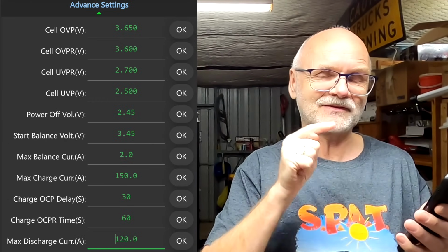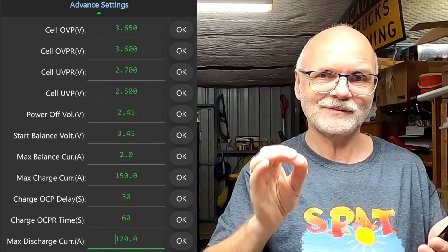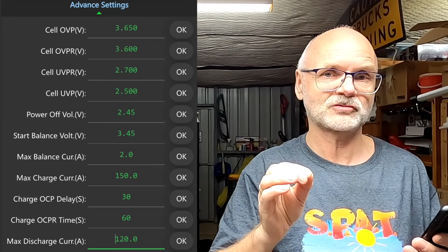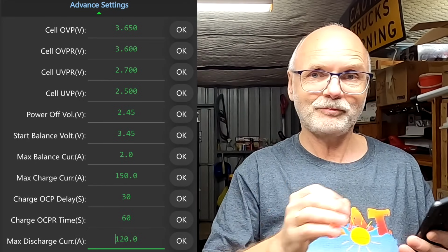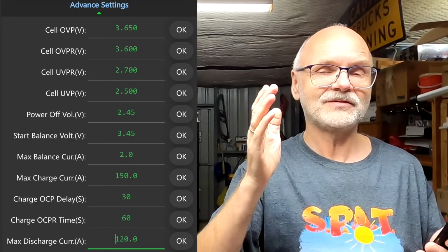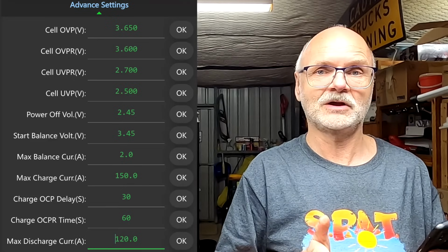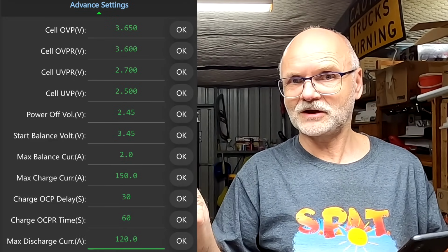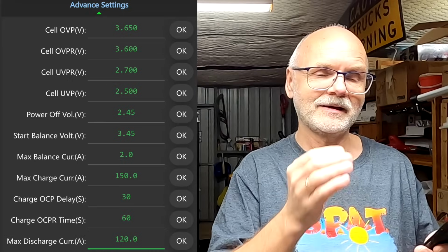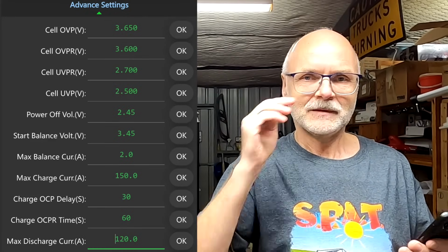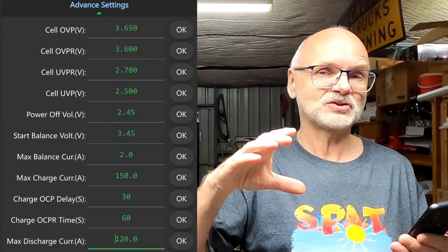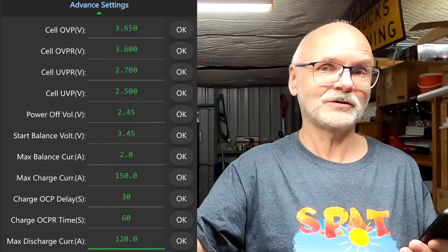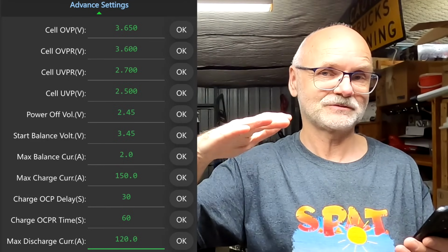It kicks in at the same time when I hit my maximum charge voltage in the solar charge controllers. So I'm not balancing before I hit this maximum voltage. My absorption voltage in the solar charge controller is also my balance start voltage, because only battery cells which are higher in voltage at this point in time do I want to discharge.